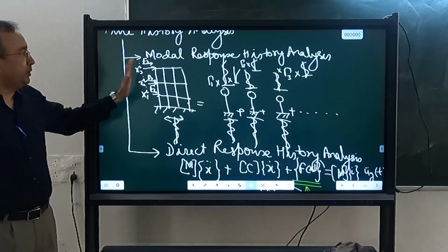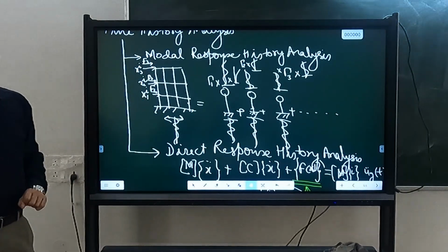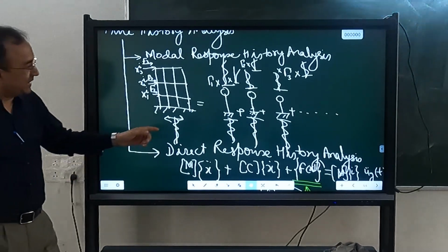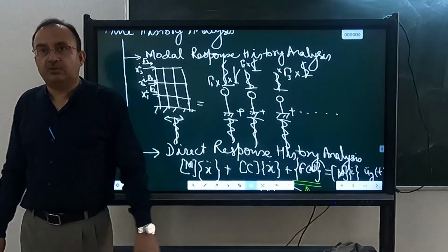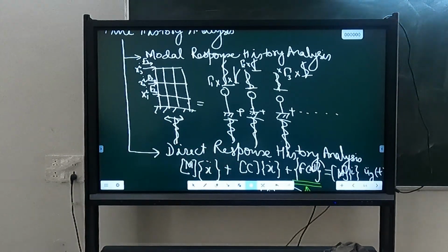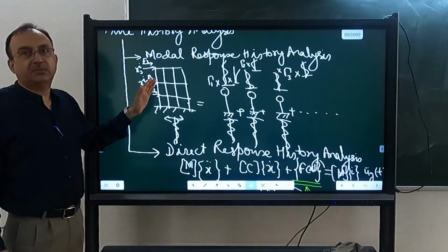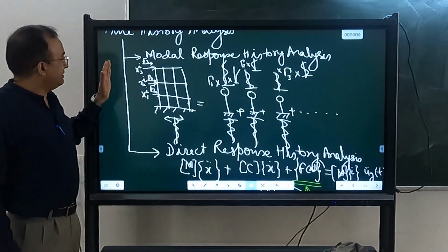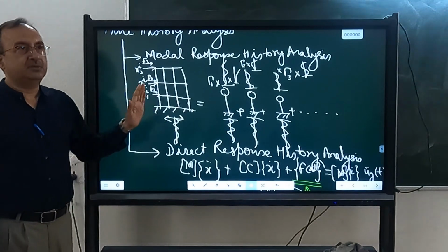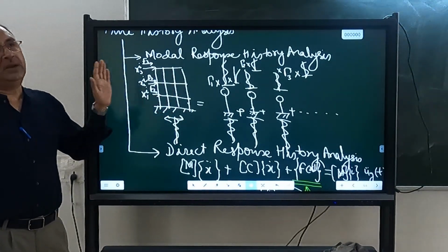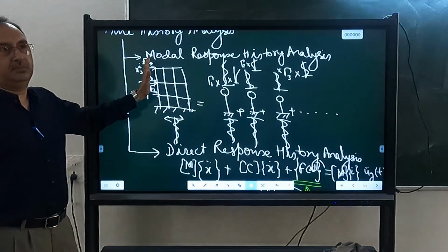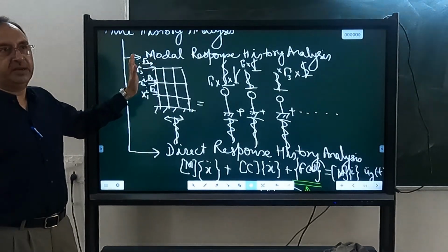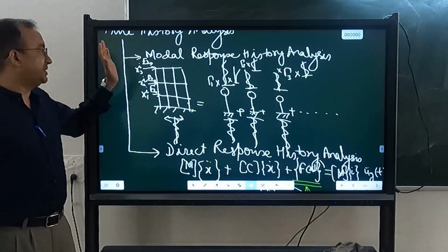Okay, but when I am doing this, I cannot apply those displacements at the same velocity and same acceleration as the earthquake, or what will be applied in the shake table. That's the limitation. So that's why we call it pseudo dynamic. I can go on changing depending on the hardware. If I have very good quality actuators and hardware, I can apply almost the same speed, velocity and acceleration. But that is not the purpose.